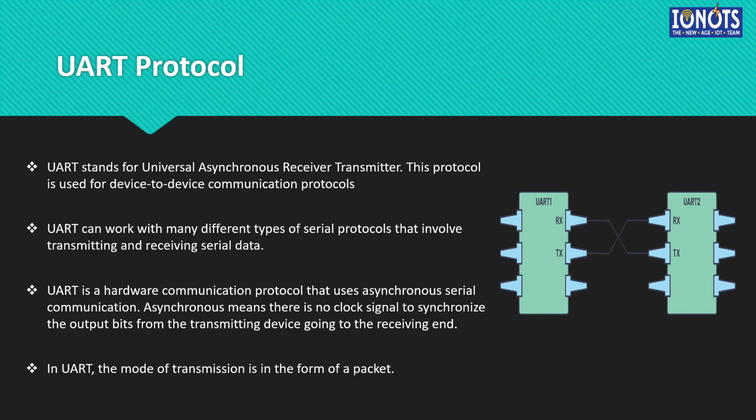Synchronization is what makes them different, and hence their names are asynchronous and synchronous, not clocked and unclocked. So that's a point of difference right over there. Asynchronous and synchronous differ in their synchronization, and the main aspect there is clock, agreed, but that refers to the presence or absence of the common clock. The devices can by themselves have individual clocks. That is not an issue.